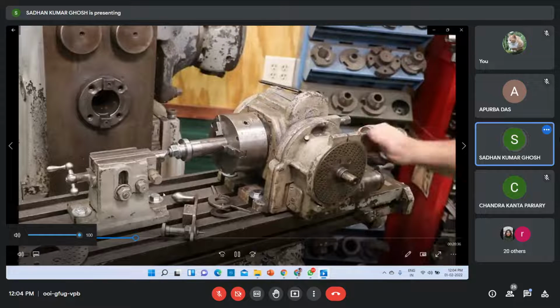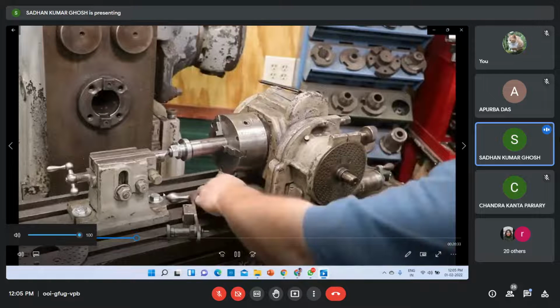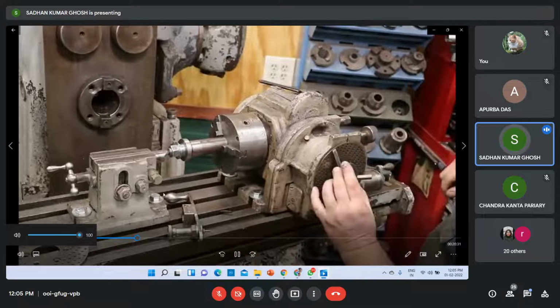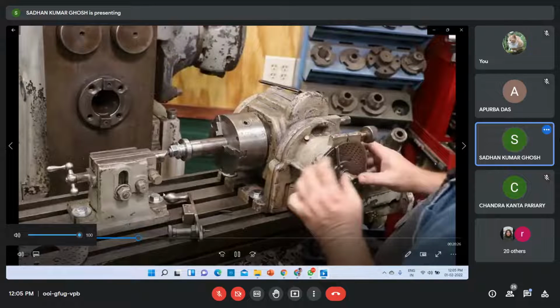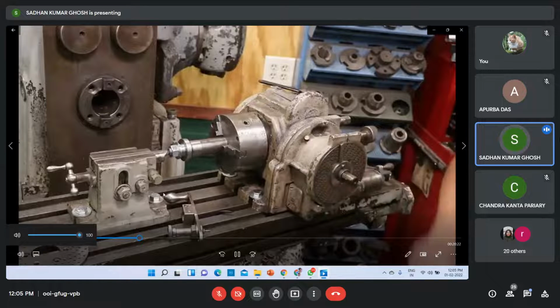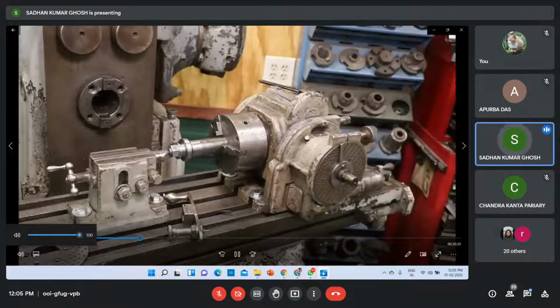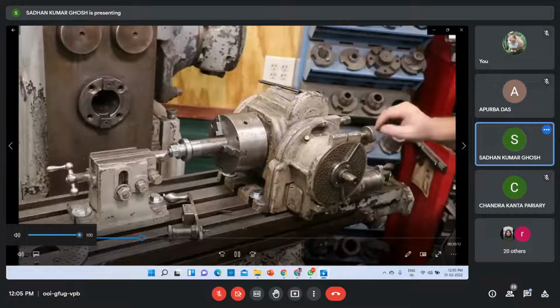Alright, got that plate back in there. Next thing that goes back on is the sector. And let me look and see. I know it's 1 revolution and some number of holes. Alright, it's 13 holes. So I'm going to go ahead and adjust this.